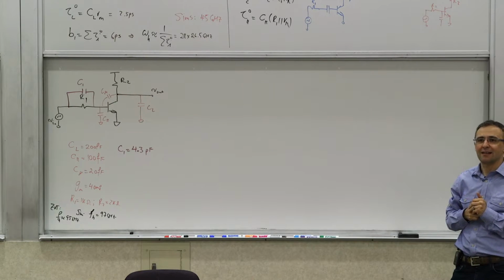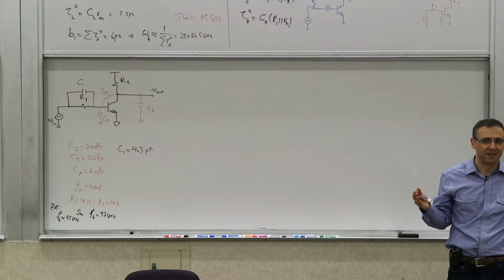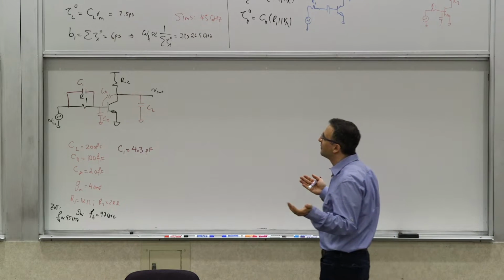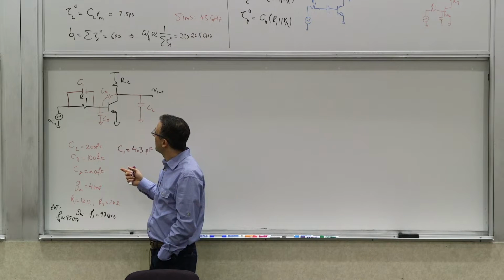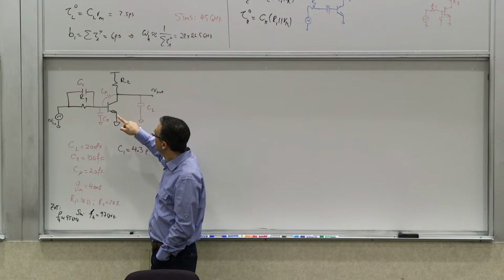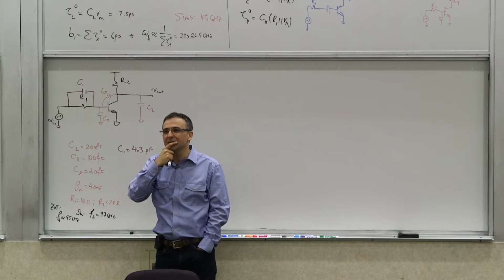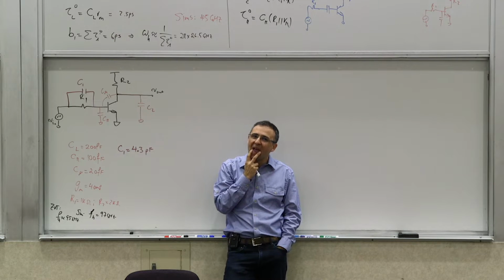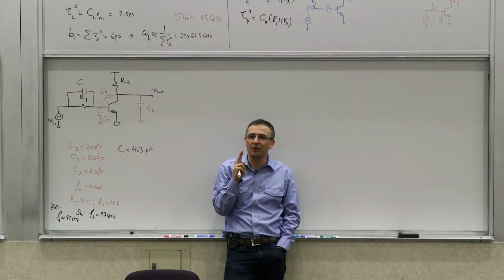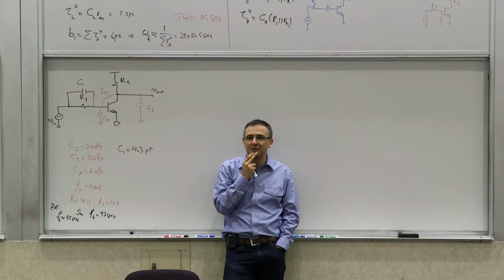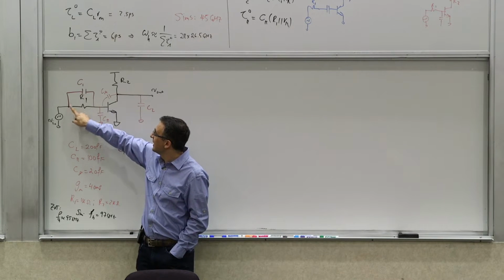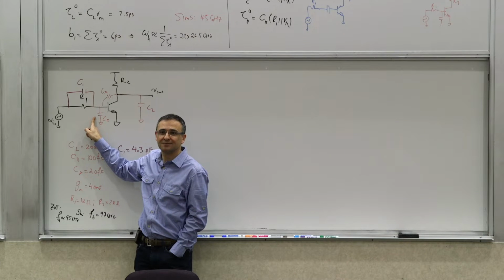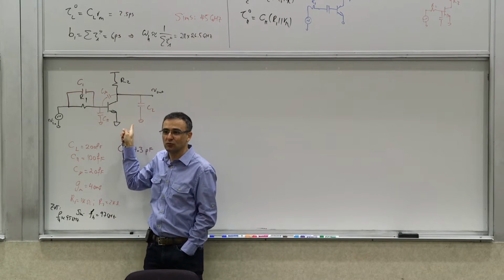Well, first of all, how many poles, how many zeros? 3 poles now, right? Do we have 3 poles, really? Let's think about it. To determine how many poles you have, you first null the independent sources. And if you null the independent sources, as far as the time poles are concerned, how many initial conditions can you make? 2 still, right? Because when I null this, these 2 capacitors are in parallel. So I still have that capacitive loop, so I have only 2 poles.